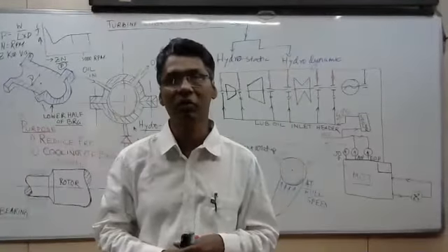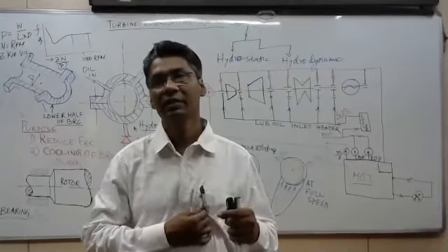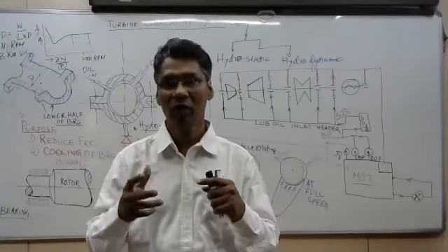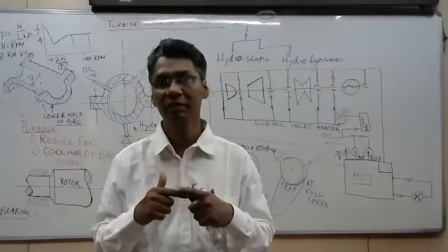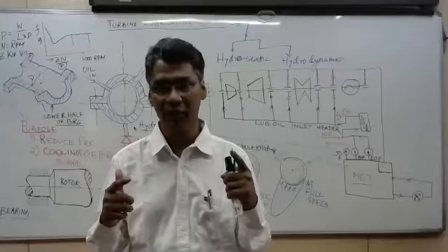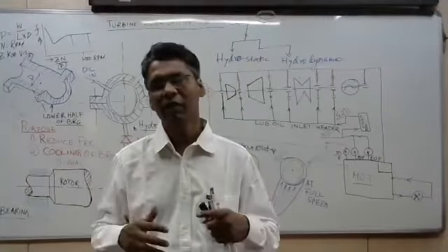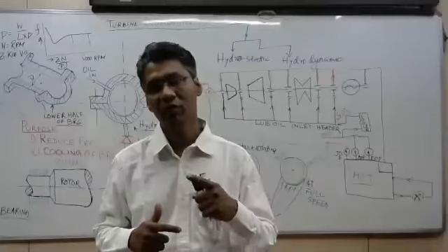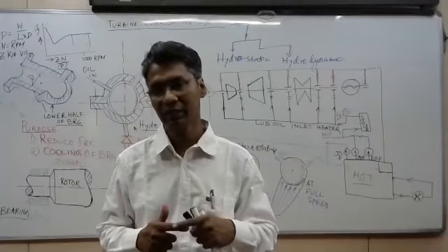It is a very simple sort of bearing where, unlike the roller or ball bearing, which has metal to metal contact, in a journal bearing at working condition there is no such metal to metal contact. That is the beauty of such a bearing, and it is noiseless, with very minimum noise, and the loss is also less compared to the ball bearing and roller bearing.